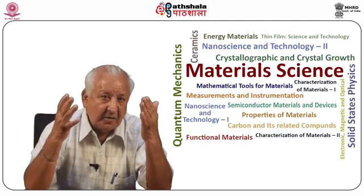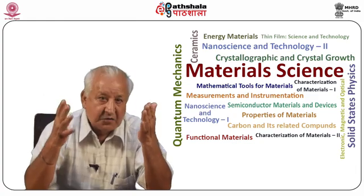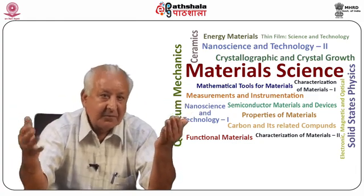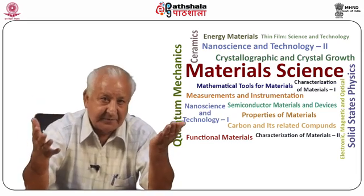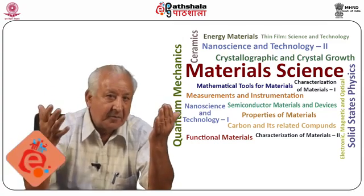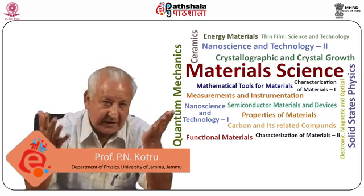Experimental arrangement of Bridgman technique of crystal growth has been described. Zone melting as a technique of crystal growth is explained. Floating zone technique of crystal growth is also described. Apparatus for zone melting or refining of materials involving volatile components is also described.